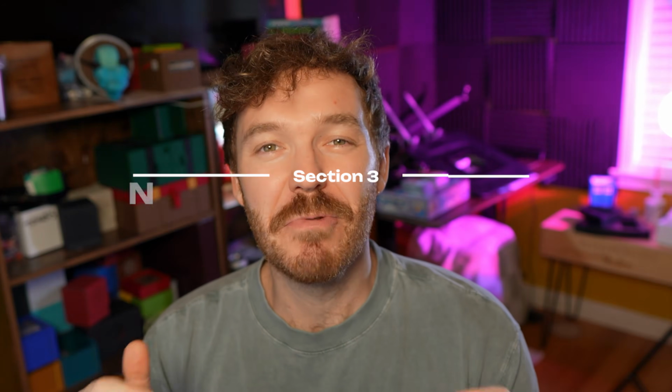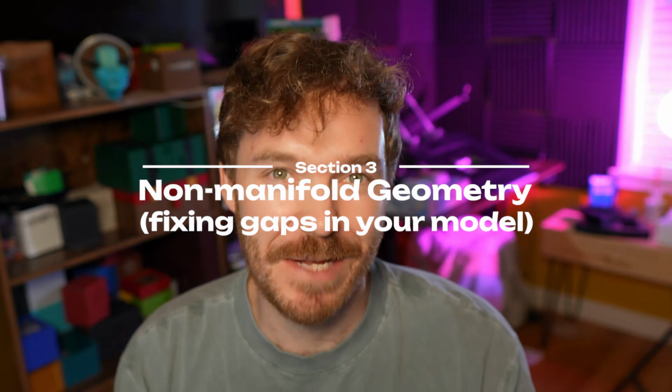Okay, mistake number 3 can be one of the most frustrating mistakes that happens in Blender, and it's one of the hardest to catch, and that is non-manifold geometry. Having holes in your models or gaps in your models. When you do that, the slicing software will try and fill those holes by guessing, and it doesn't always get it right, sometimes resulting in the model not printing at all, or mistakes and weird things happening with the model. It's very frustrating. So I'm going to show you how to fix that.